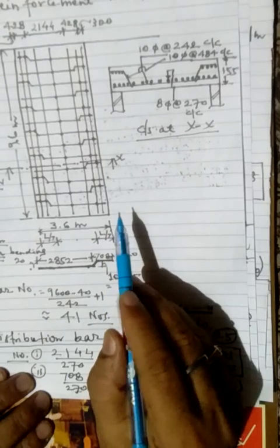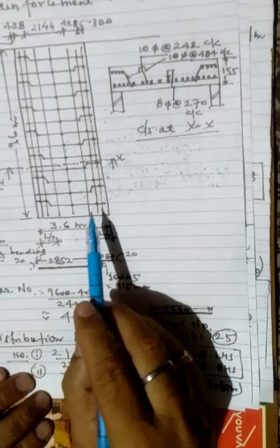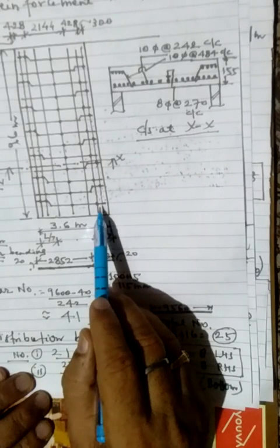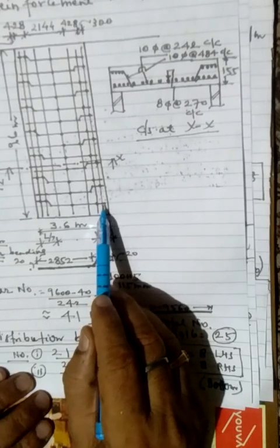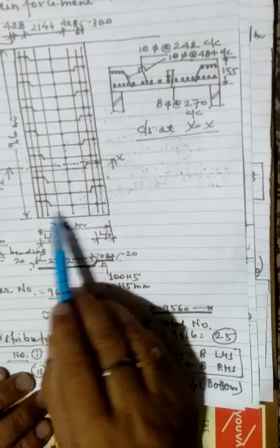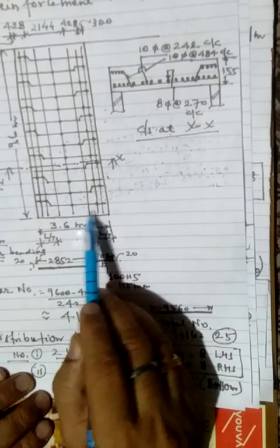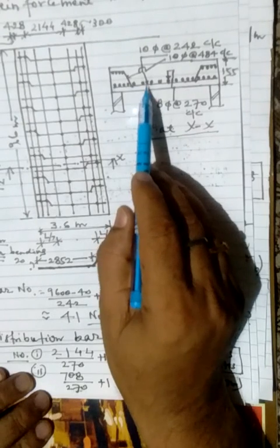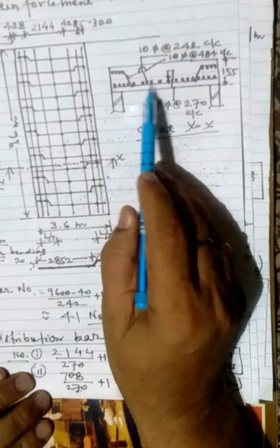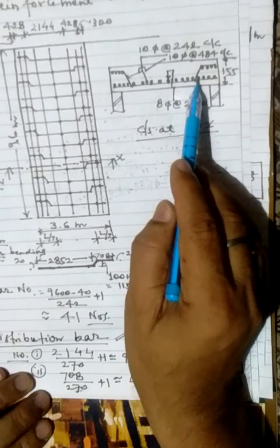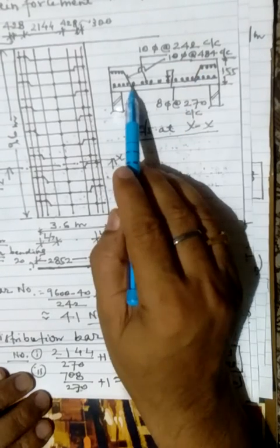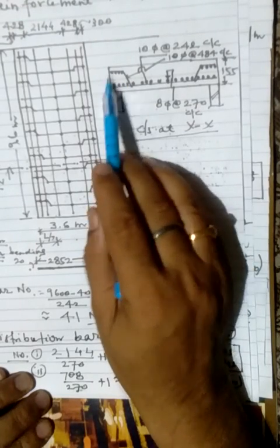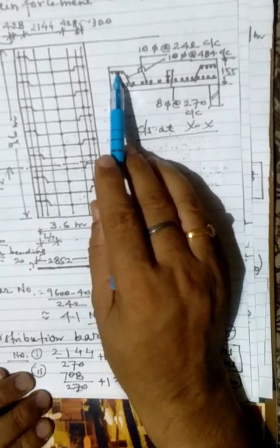In this slab, suppose for providing the main steel. Now main steel area is generally provided in the bottom of the slab, that is bottom steel is nearer to the tension face, that is the bottom face is the main steel. So main steel is having top bars, it is bent up at the support and it goes to the top of the support. So near the supports, 50% of the steel goes on the top surface.